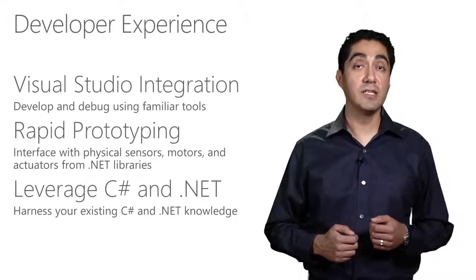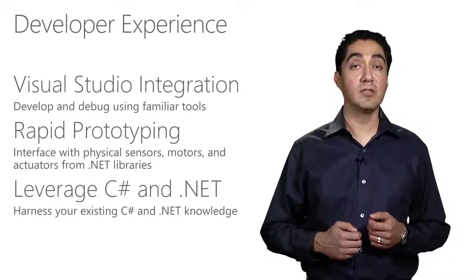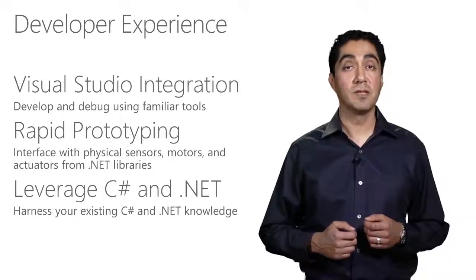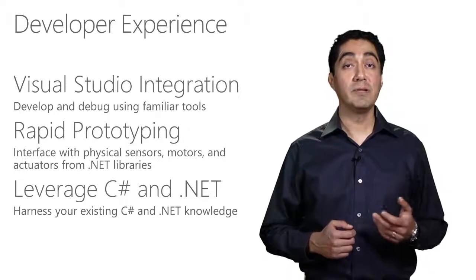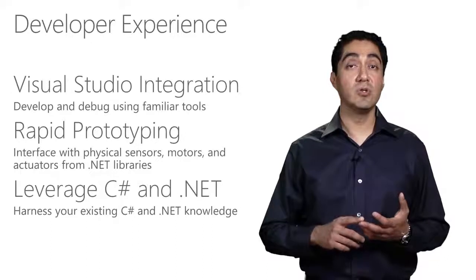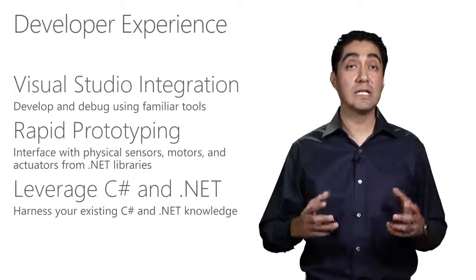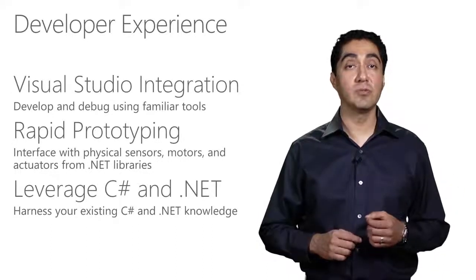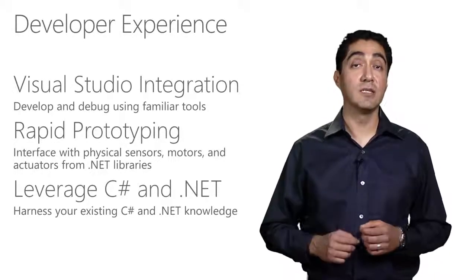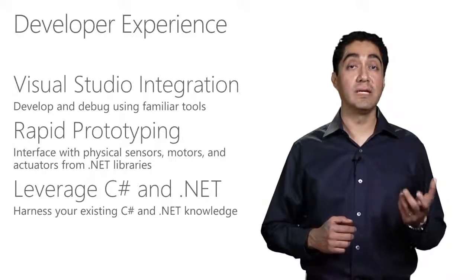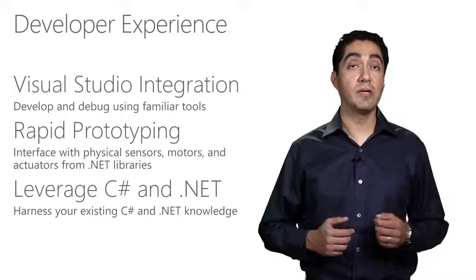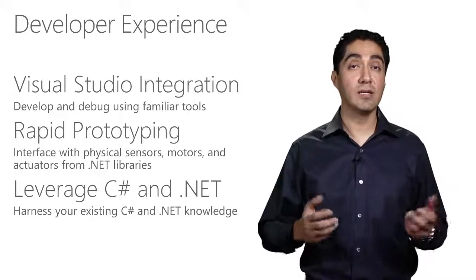As a developer, you can take advantage of the same development and debugging tools of Visual Studio to easily write applications for microcontroller-based devices. The Microframework provides .NET-based libraries for common serial buses such as SPI, I2C, and traditional UART to interface with sensors, motors, and actuators. Application developers can interface with those peripherals without having to know the intricacies of the microcontroller running on their embedded device. In addition, developers can use Visual Studio, C#, and their .NET knowledge to quickly write embedded applications.